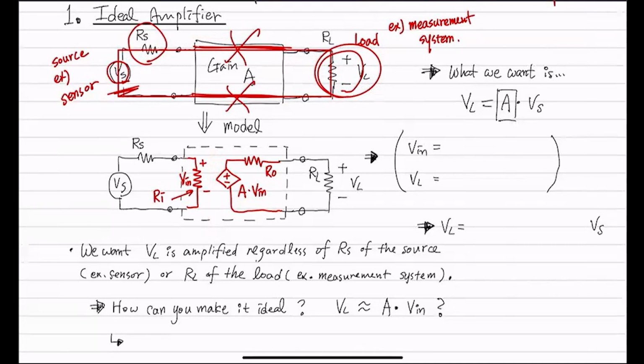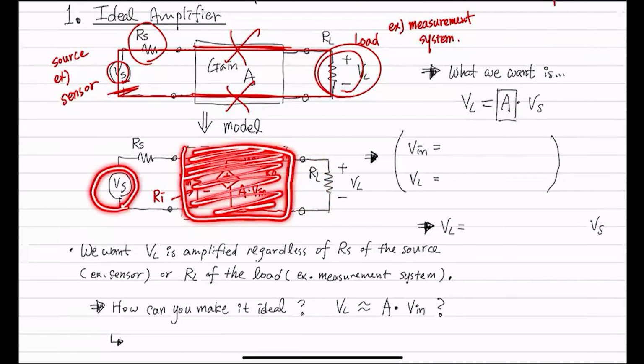So it has a closed circuit here and another closed circuit there. Somehow, from here to there, the voltage across this resistor is being amplified by a transistor actually, and it becomes A times Vn. This becomes a new source to run this circuit. We don't know what is inside, and we actually don't care. All I want is for this to be boosted up so that I can measure it over there.